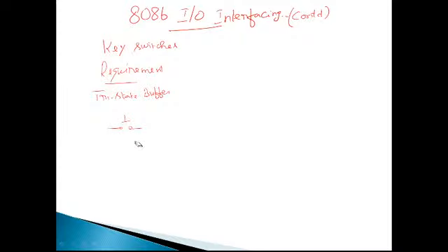Let us assume that it is a push button switch. The same thing is applicable to other kinds of switches also. The requirement here is that we need a non-inverting tri-state buffer, and this should be taken to the processor. As I have told you several times, in the tri-stating buffer the output follows the input. Whatever is available at the input is going to go to the output.